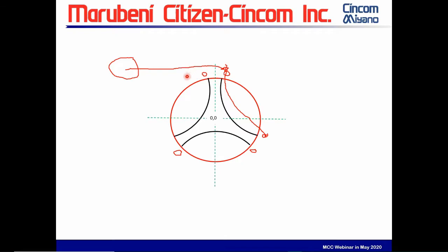Just so you could get an idea of starting out, going over to the first point. So basically this part has 1, 2, 3, 4, 5, 6 points, and 7 points if you count going off the part over here. And there'll be 7 lines of code to create this part. Okay. And everything's based off the 0, so you have it jumping up to here, here, and here. Yeah, I'm repeating myself on that, but I can't stress it enough.